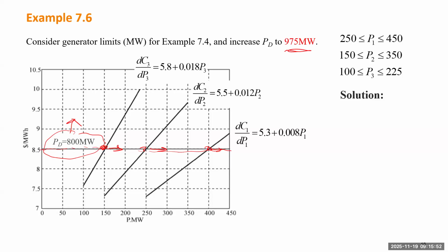If there's no limit, you can feel free to go up and down until they always give you the total load. But when each generator has an upper limit and a lower limit, when you move up, there's one possibility it will reach one of the limits for some generator. If that happens, stop that machine there. Like if you move up to this level, the 3rd unit will reach the upper limit. Don't move it further, but continue this process for the other units, because the other units have not reached the limit. So they just optimize as a problem without limit.